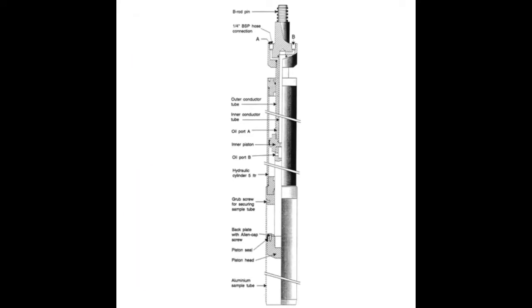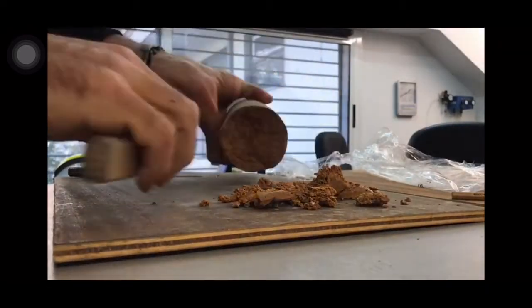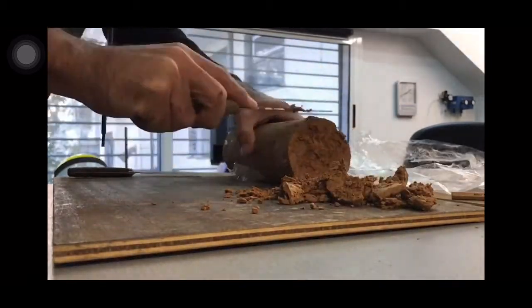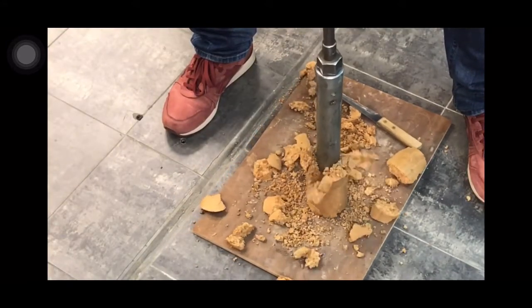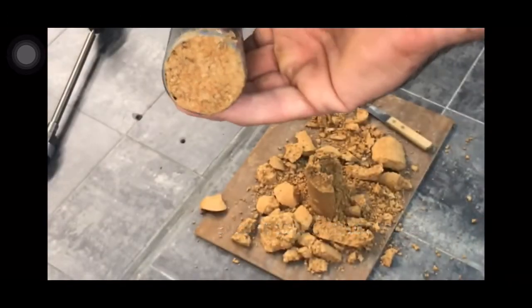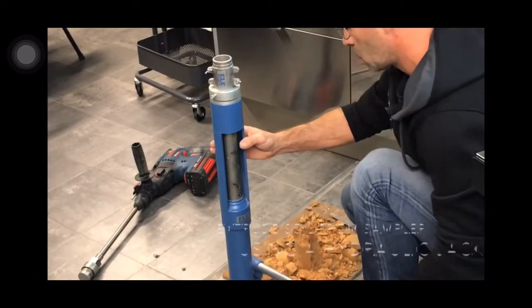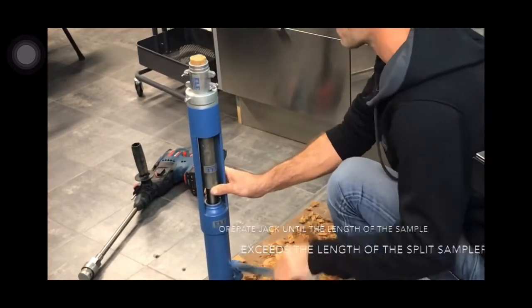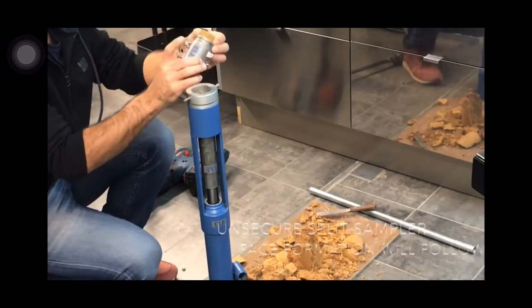The process: using a triple wall core barrel permits removal of the sample as it is taken from the ground, guaranteeing the in situ condition of the core. That's why these samples are, in addition, good for large diameter geological laboratory tests beyond geological purposes. The inner tube is made of plastic and continuously covers the sample. The wire line system allows only the core barrel, second and third tubes to be pulled out to the surface after 1 or 2 meters of core drilling, while the other tube, the first, works as a casing.